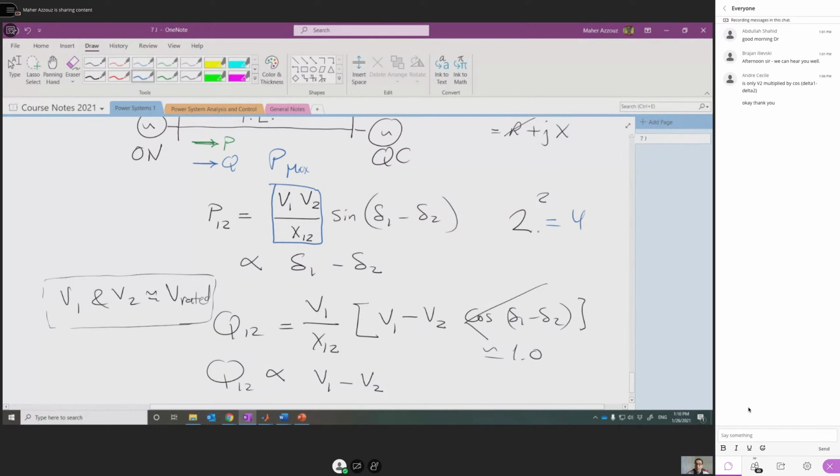And this will help us reduce the need for land to install transmission lines, and decrease the power density of the transmission line. But of course, as you double the voltage, you have to double the height of the tower. Because as I told you before, we use the air to act as an insulator between the line and ground.